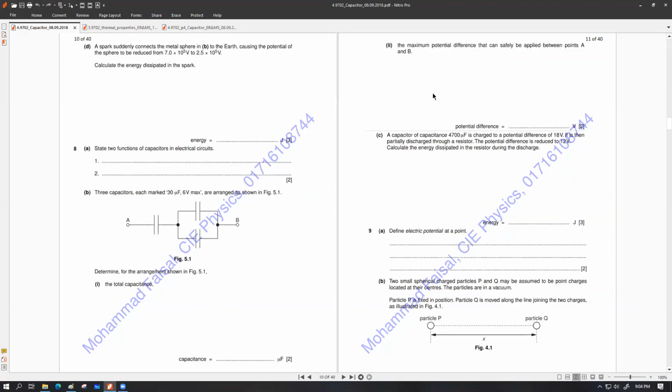The charge for the disconnected part would be equal on both sides, but it can get divided depending on how many you have connected. If we have Q charge over here, each of these capacitors should have plus Q by 2 and Q by 2, because here is one plate and here we have 2 plates connected. So that's what I mean.